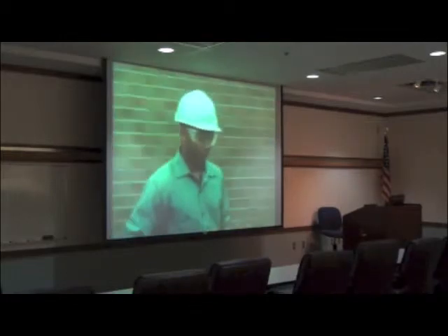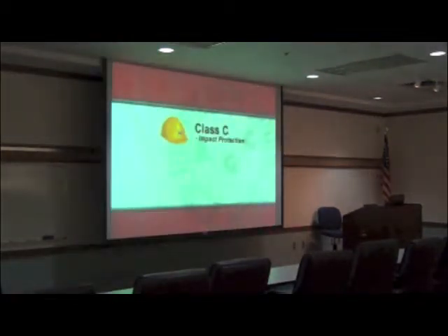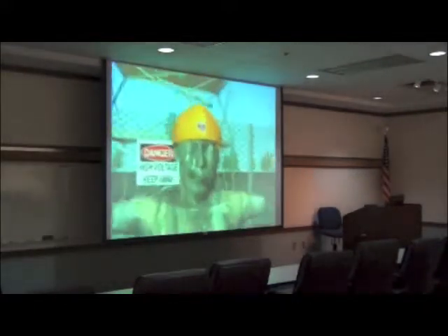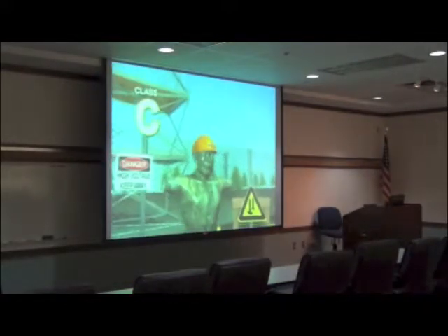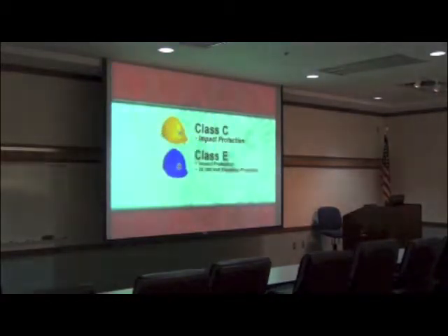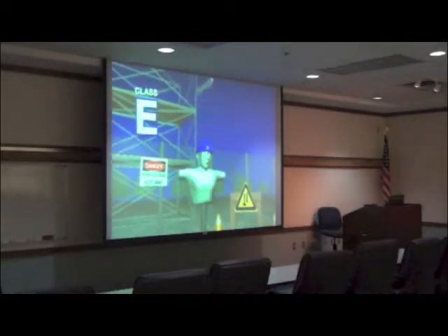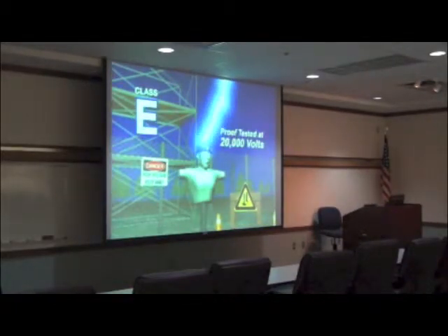Wear a hard hat that is appropriate for the hazard. Class C hard hats are intended to reduce the force of impact of falling objects, but offer no electrical protection. Class E hard hats are designed to reduce the force of impact of falling objects and to reduce the danger of contact with exposed high voltage electrical conductors. Sample shells are proof tested at 20,000 volts.